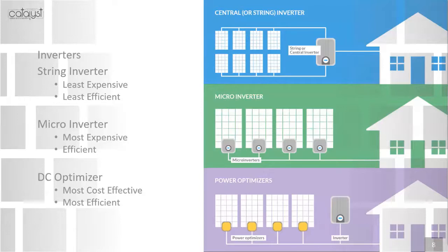And then in 2015, 2016, we saw a company out of Israel, actually SolarEdge. They took the best of both worlds. So they took the benefits of maximum power point tracking, they took the benefits of module level electronics, and they came out with a power optimized or DC optimized system. Now I still have DC coming off the roof. I still have a single inverter, but I put power optimizers on the back of each module.